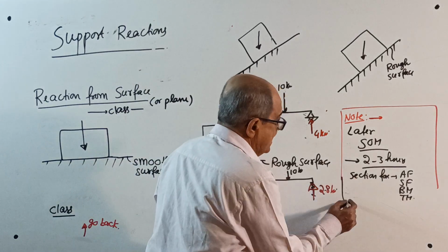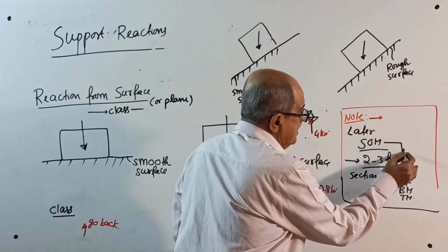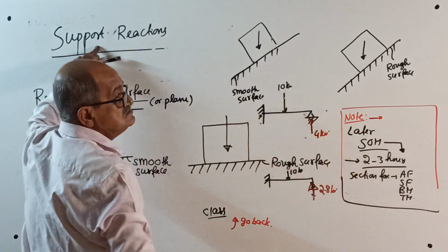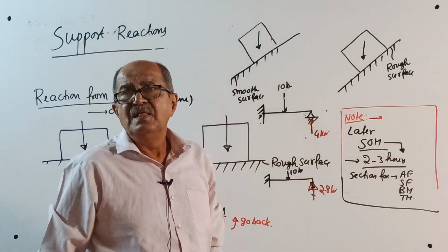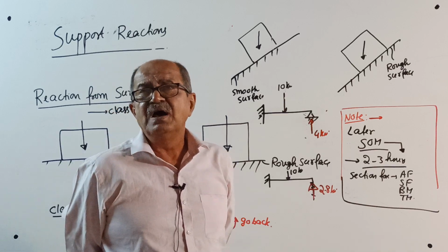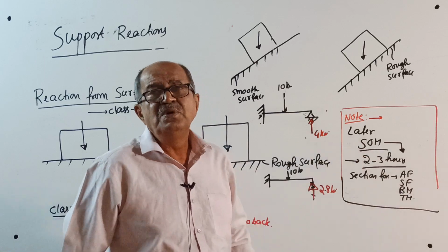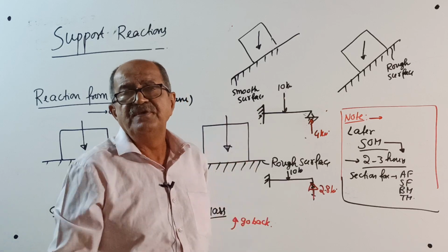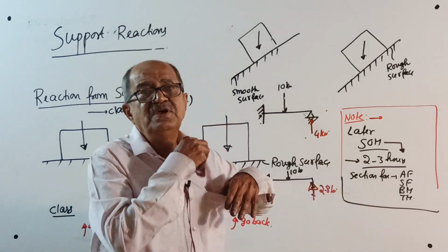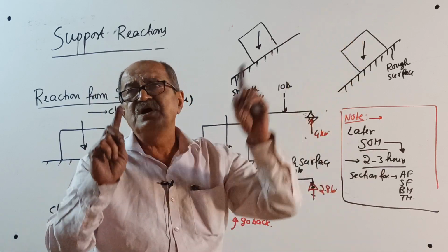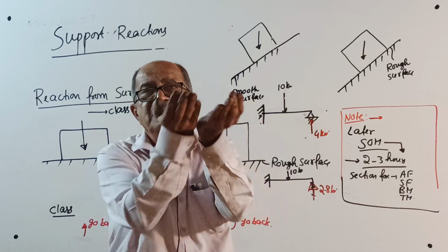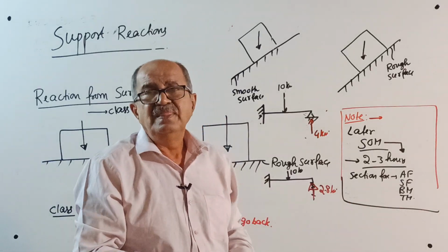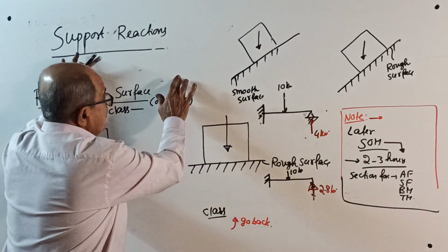Therefore, this time when I go to strength of materials, starting, I will explain each and every concept of support reaction and equilibrium once again. Then some of them are direction based, some are nature based. When you do equilibrium, you consider direction, right side, left side, upward, downward, clockwise, anti-clockwise. But when you do section forces, you don't consider direction, you consider nature, compression, tension, bending, sagging, shear, twisting, etc. This all I will explain. Therefore, right now, what I told is sufficient.